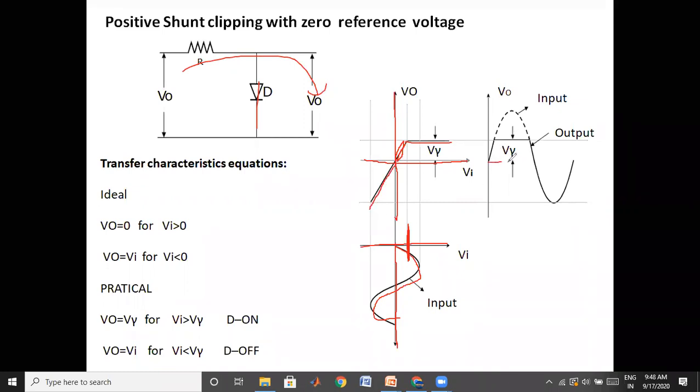Here also, in a similar fashion, this waveform which we have drawn previously, we had taken as ideal. Therefore, here we have mentioned the zero voltage, zero and the negative cycle. Like this we have drawn. In the previous case, if I take a practical diode, then we may have the output up to the cut-in voltage, 0.7. Up to 0.7 the diode won't turn on if it is silicon. If it is germanium, the voltage may be 0.3. Your diode will switch on at 0.3 volts.